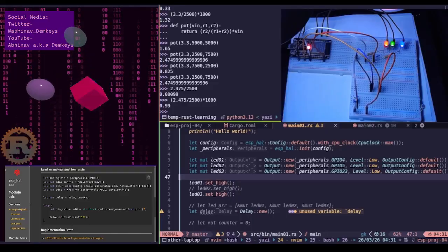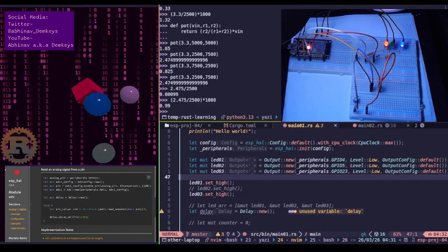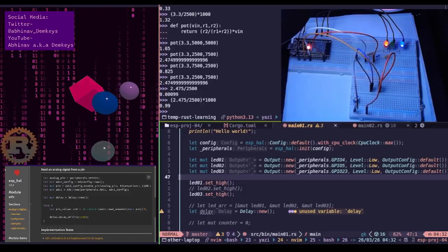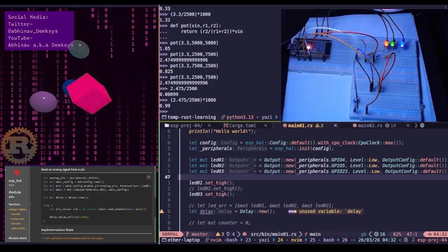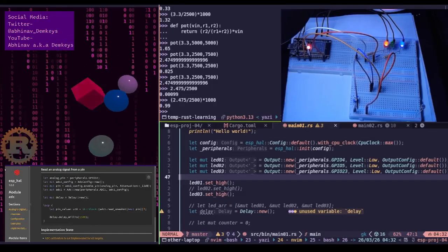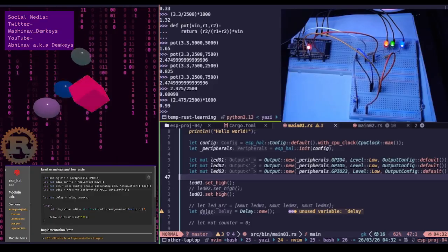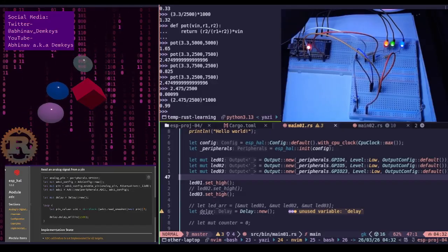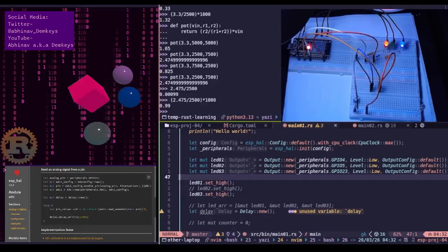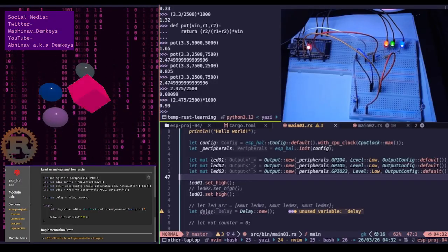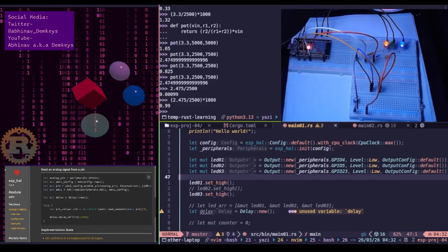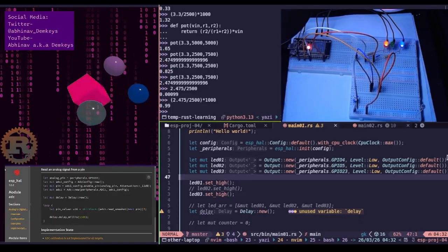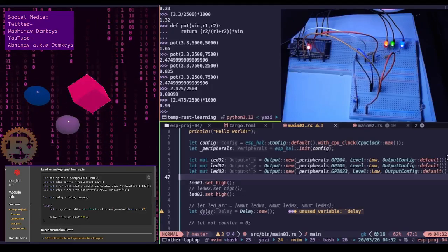So if the range here is meant to be 0 volt to 1.1 volt, and this range is then meant to be translated to a range between 0 and 4095, is it possible that when we try to use a range of 0 volts to 3.3 volts on this pin that is configured to do 0 volts to 1.1 volt, it's going to keep going?